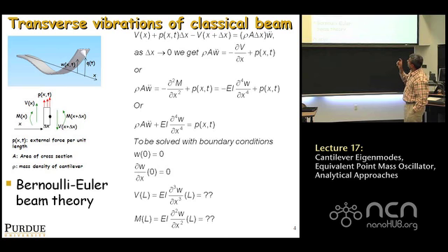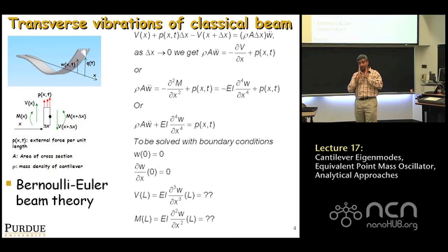Now, what we do is we take a section at a distance x, so we make a virtual slice through this beam at a distance x, as shown, and we make another slice at x plus delta x. So this little rectangle you see is basically, if you will, you've made a slice through the cross-section at x, and another slice through the cross-section at x plus delta x. You got two open faces, if you will. On the left-hand side, you got the shear force V(x) and the bending moment. We've done all this when we did static bending analysis. It's the same thing, no difference. And then you have the bending moment and the shear force on the right-hand side, and you have the external load P(x) acting on that little sliver, right?